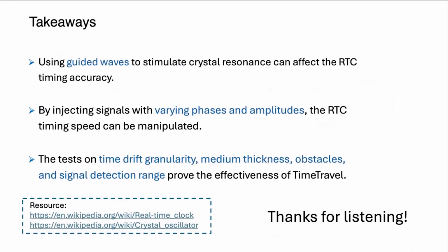So, in a nutshell, in this work we found that guided waves can affect the RTC crystal's oscillation by applying signals with different initial phases to induce additional resonance. The edge triggering moments can be changed, thereby affecting the RTC timing rates. Then we conducted extensive experiments to test the effectiveness and robustness of this kind of attack. For more details, please refer to our paper.